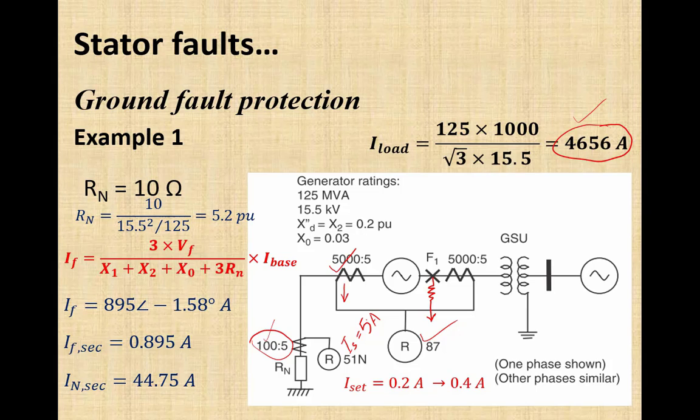So this was a statement that we have discussed previously. Now if I summarize over here, in case of a solidly grounded neutral, there is no need to use any dedicated protection in the neutral circuit. The phase fault relay can easily detect the ground faults.